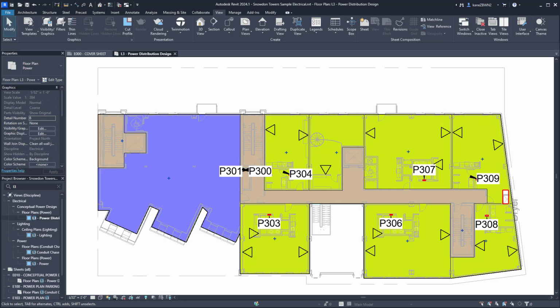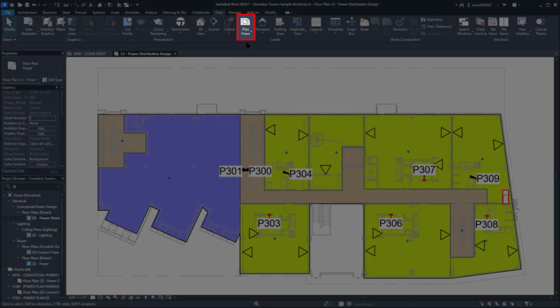Let's talk a bit about navigating the different Revit views. We'll cover creation and modification in a later video. For now, this is just familiarizing you with the controls to get around your views. First, a quick overview of the different view types. There are plan views, which have a few subtypes. First is the floor plan, which is what's currently open. As you can see, it's a top-down view of the floor and things inserted on it.